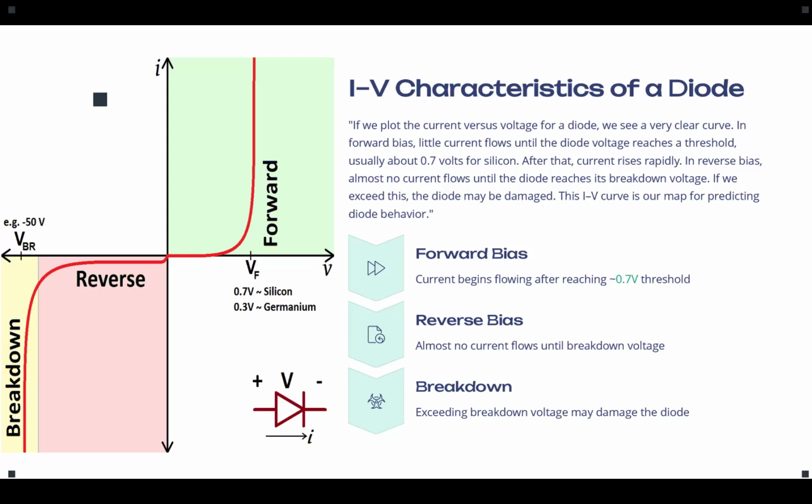In a silicon-based diode, that voltage is 0.7 volt, and in a germanium-based diode it is 0.3 volt. So if you have a sensitive circuit where you need the diode activated at a lower voltage, that says you need to use germanium instead of silicon.